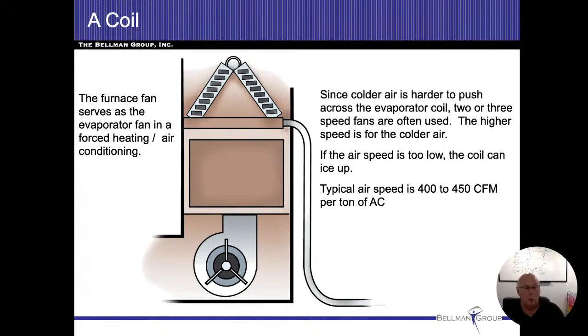All right. So when you're going around and you've got the air conditioning running, try to hit every single room and make sure you've got a decent airflow coming out of there. Some people, and Mark, if you're still here, I know you're going to know this answer, use a wind or airflow monitoring device, and I'm drawing a blank on what that's called right now, but they put that over the ductwork, and I kind of like that idea because now we have a definitive number. And if we have one room that's significantly less than the rest of them, that could be an area where we're going to have trouble heating or cooling.